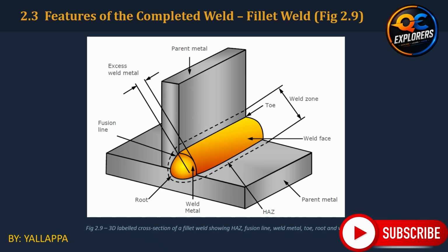From an inspection perspective, do not judge a fillet weld only by whether it looks large. A large weld is not necessarily a good weld. The inspector must consider the specified weld size, profile, fusion, penetration, toe condition and applicable acceptance criteria. That is why correct terminology and measurement are essential.